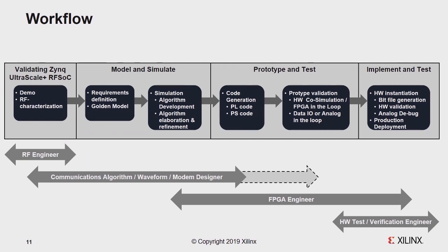And then you're going to basically build something, and there's two types of simulation that people do. There's what we call hardware co-simulation or FPGA in the loop. So you'll basically build something, program it on the FPGA. You'll run something on the computer or MATLAB. You'll run it through the FPGA and see if it works.